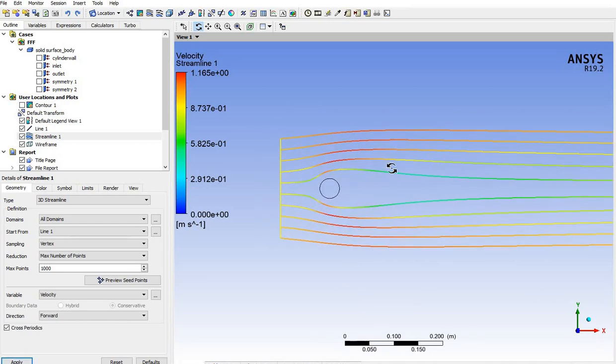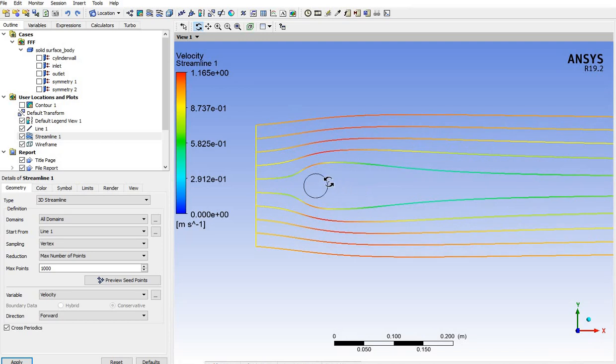You should see the vortices, stable vortices forming at the wake of the cylinder, as I have shown you guys. If you just search in YouTube how the flow around this kind of cylinder would be, you can take a look, and for the laminar flow, you should see some stable vortices forming over here. And for turbulent flow, it starts shedding the vortices. Okay, so do use this kind of tool